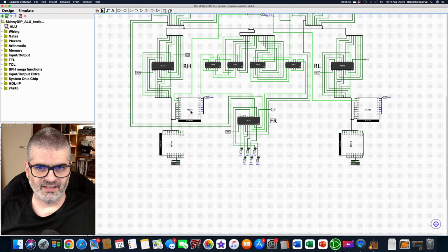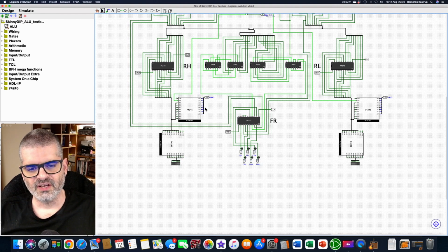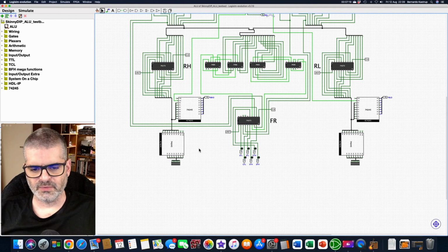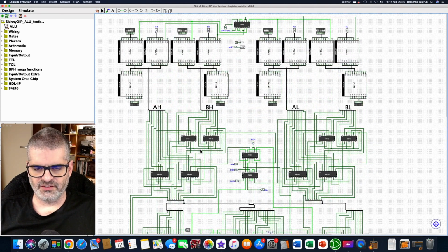And because they are strong drivers, the rise time tends to be relatively short, which means that the higher frequency harmonics are rich. There's a lot of higher frequency harmonics every time you switch these signals. So the 33 ohm resistor networks are just meant to dampen those oscillations down, dampen the ringing down a little bit. And that's it. That's the circuit.